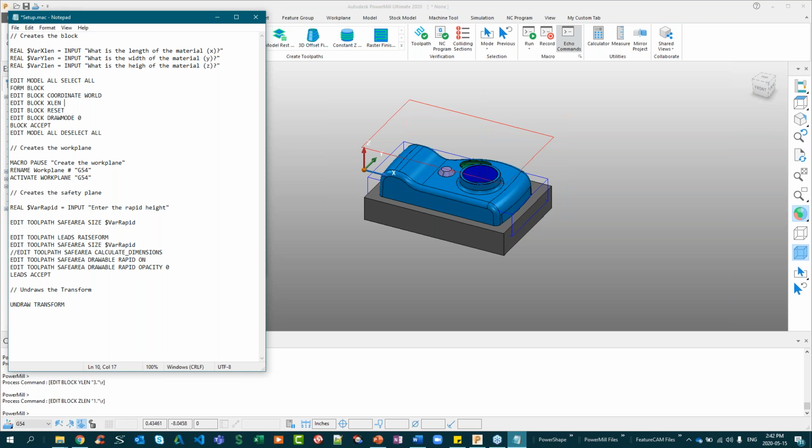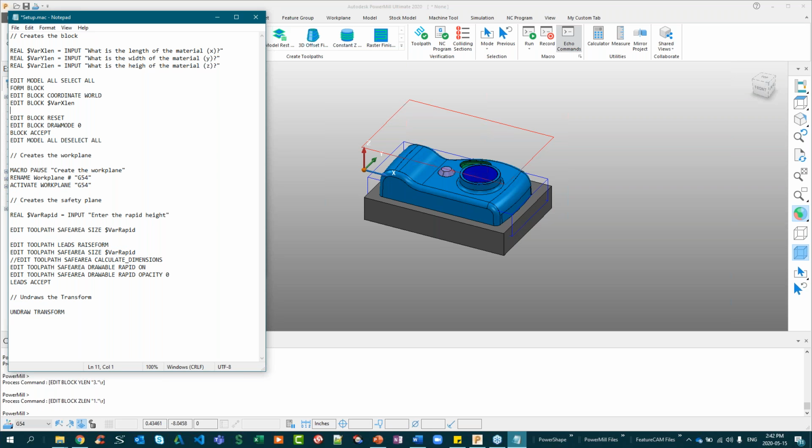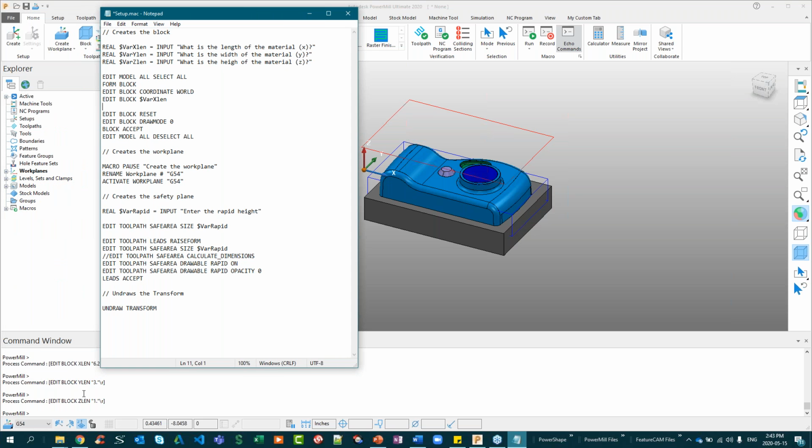and the length is going to be our variable. So block length is going to be this. It might even be a good idea to copy and paste this so there are no spelling mistakes, like so. And then we'll do the same thing for the Y. Actually, I deleted something I shouldn't have. I should have block XL, X length in there. Otherwise, that is not going to work. So XEL, LEN. There we go.